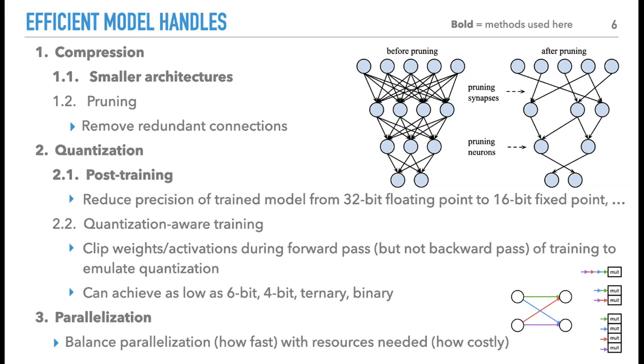So what this little diagram on the right shows is the difference between a reuse factor of 1 on the bottom, in which you assign a resource to do every single one of the multiplications in parallel, versus a reuse factor of 4, for instance, where you reuse the same multiplier unit 4 times. And so then, if you were going to do another one of these computations, you'd have to wait 4 clock cycles before you could reuse that same multiplication unit.